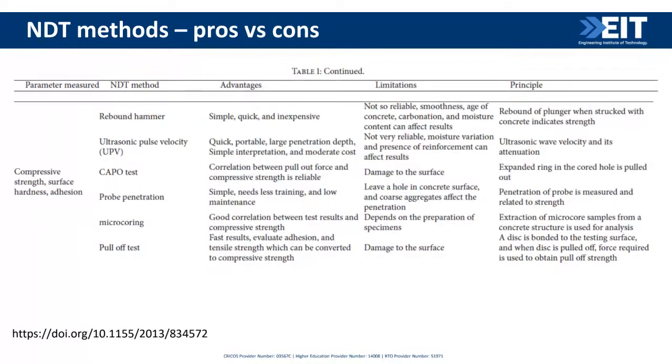In a sequence, we can see now, for example, very fundamental, the fundamental for us is in relation to compressive strength, right? Majority of time we are targeting compressive strength because it's the simple way to understand the structural condition. And these are some of the non-destructive tests, as I could share: rebound hammer, ultrasonic pulse velocity, and there are some ideas when you can use, for example, ultrasonic.